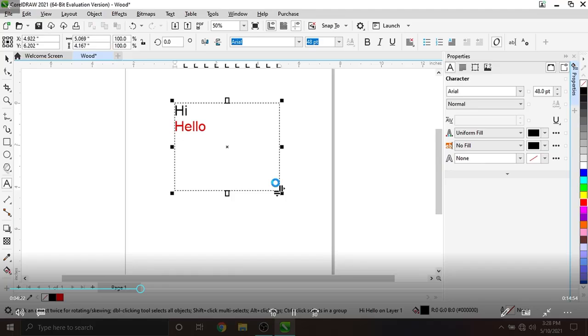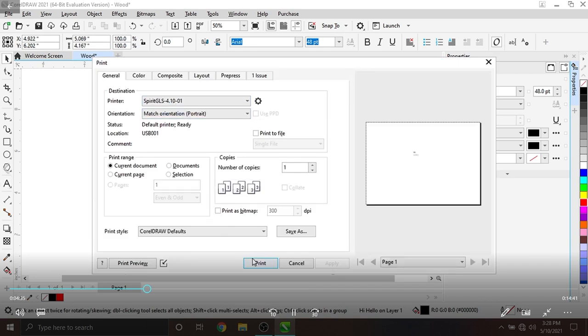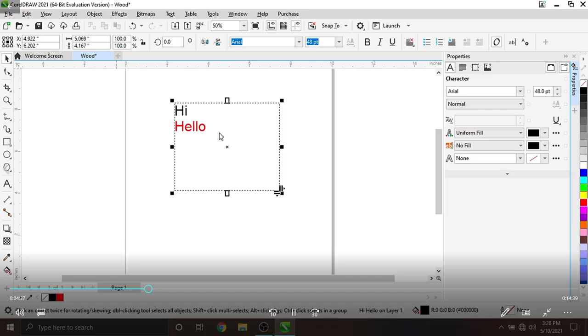Same thing. This is mainly for wood. Different types of wood will have different types of coloration. But the best I found on plywood is 50 power, 50 speed at 400 PPI. Again, just hit print, send it over to the printer, and you'll wait.